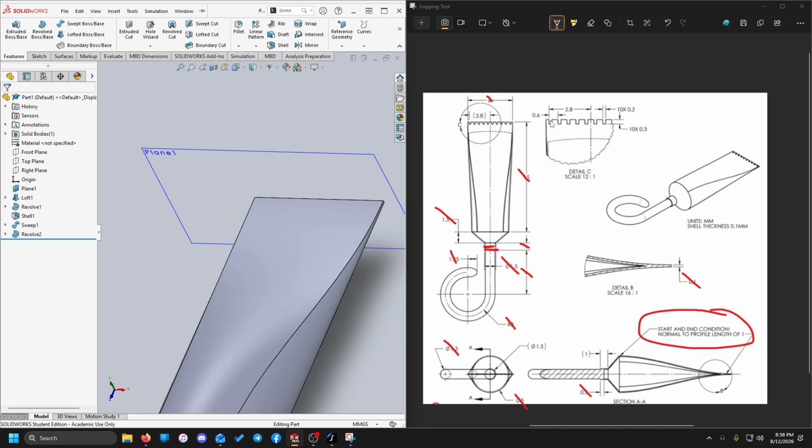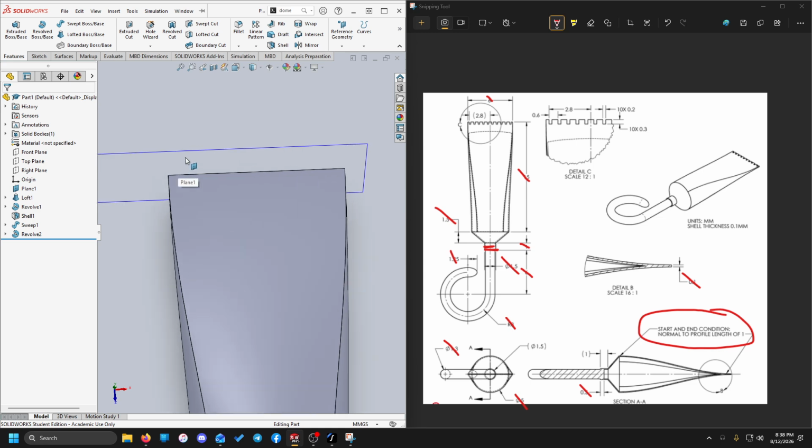Alright, so the last bit that we've got is this little pattern on the back of our tube. And for that, we've got these little rectangular cutouts, and it looks like we've got 10 of them. So let's begin by creating one of them, and then it looks like it's probably going to be a pattern just to get the others, because trying to do this manually would be rather tedious. So in this case, we can pick one to start with, and then pattern out from there. Pattern works best if you choose one of the instances that's on an extreme, so here probably just picking this leftmost notch is going to be the easiest, and then we can pattern it with that 0.6 spacing to get over to the other side.